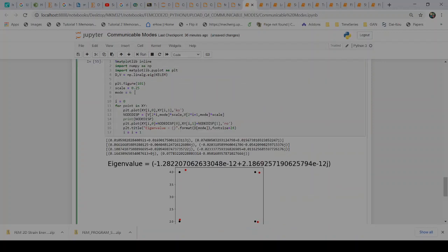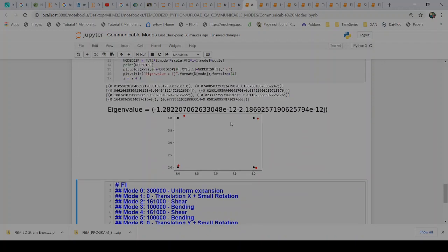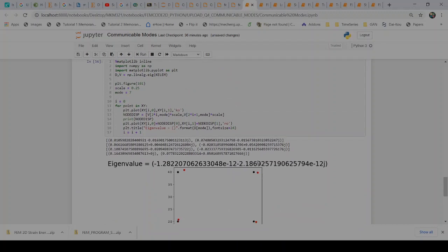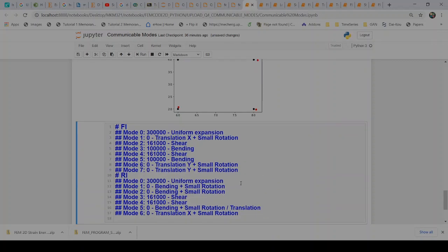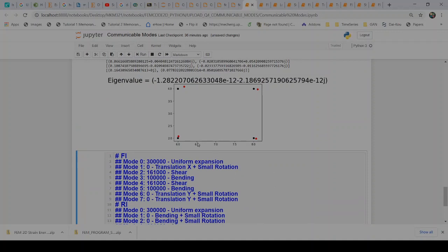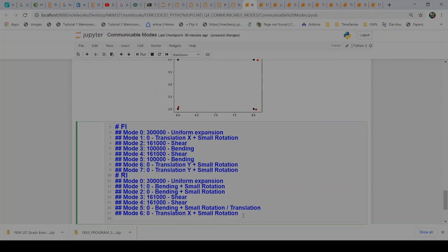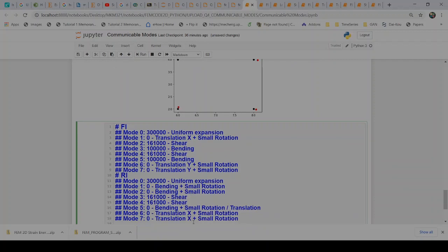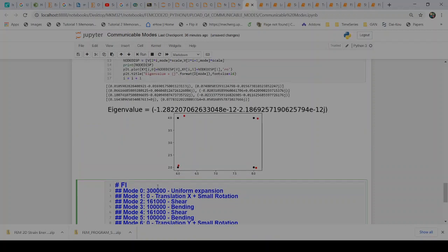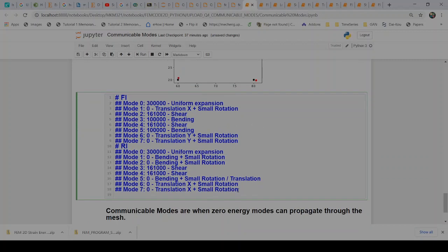And then lastly, look at this, again a zero energy mode. And again it looks to me like some rotation slash translation. Rotation, translation kind of mode. So maybe translation in Y. Oh, so in X, yeah. That's X, because these points have moved to the right, and then some more rotation associated. It's something in that regard that we see.